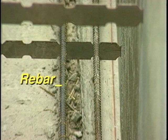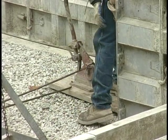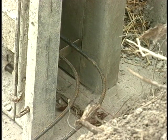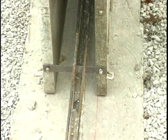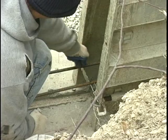Rebar is thick steel rod. It is commonly run along the top and bottom of poured walls. The rebar is placed on the metal ties. Notches in the ties allow you to wire the rebar in place so it will not move during the pour.